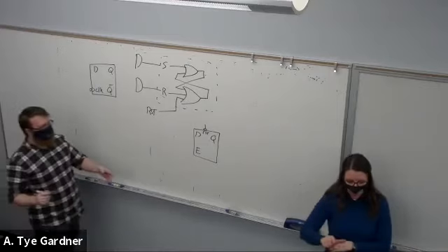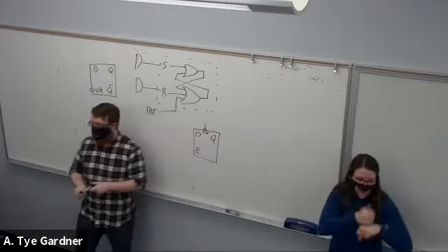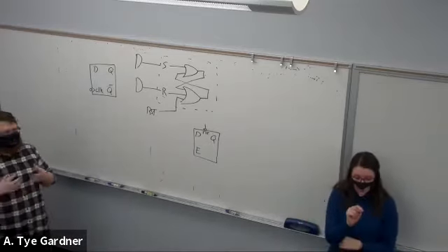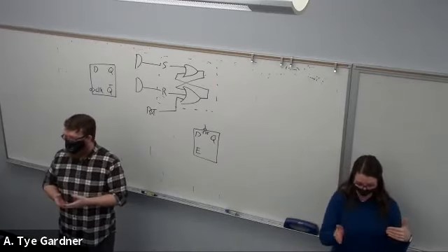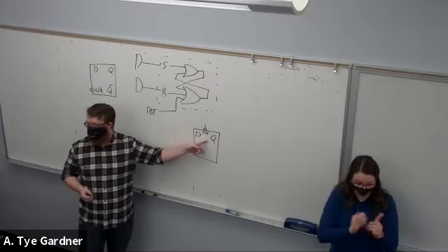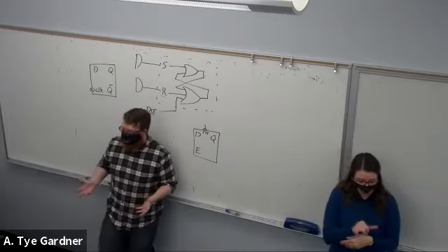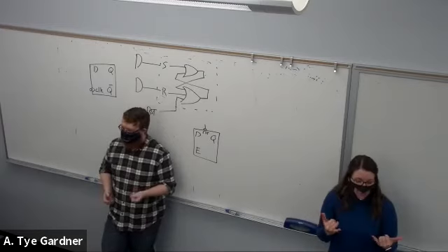All that's doing is saying I can now set this to 0, so Q is 0. Resets, in general, are very important for sequential logic, and most of the time you're going to design them as active low. Part of that reason is that it's just become the industry standard. The other reason is it's actually really beneficial from a circuit standpoint.